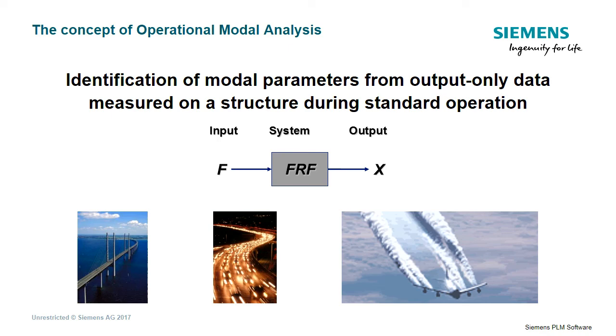This allowed identifying modal models from structures being in operation, relying solely on response measurements. It is applicable in those scenarios where the forces acting on the system have a random profile, meaning their frequency response is flat. In those cases, similar modal parameter identification algorithms exist. If the excitation profile doesn't comply with the requirements, the estimated modal model will be less reliable.